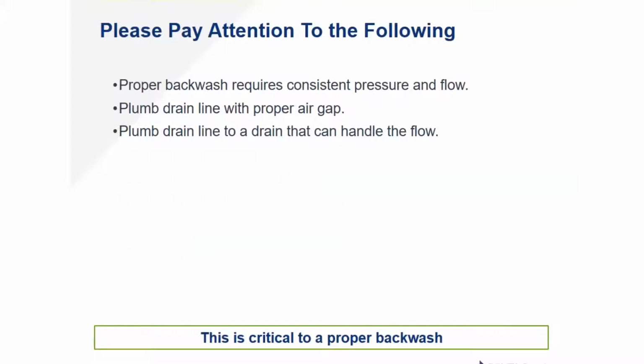There's a particular quick service restaurant out there that does not recommend water softeners to its franchisees because of this drain line flow issue, because they have grease issues with their drains clogging. So they don't recommend softeners. I've seen some of their locations actually have the softener drain line routed outside to a French drain because of their sanitary sewer issues clogging with grease. So it can be a particularly problematic issue in certain facilities.